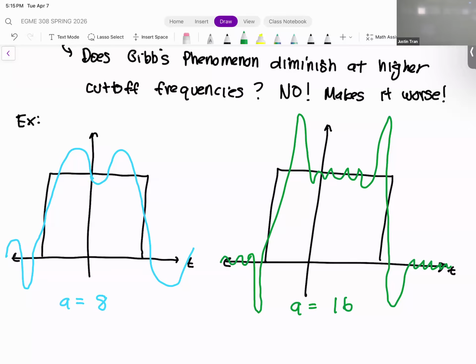So you have to cut it off at some point. And the temptation is going to be, let's just keep as many frequencies as possible. But if you do that, it's more susceptible to things like this. So there's a balance of keeping enough modes so that our signal is accurate, but not adding too many modes, otherwise it blows up.